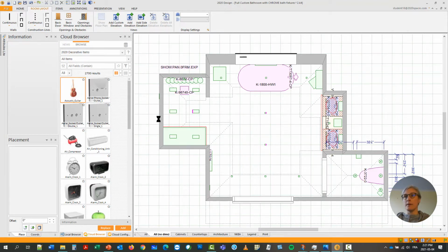The first step is to create a hole. But just before you create a hole, something that I recommend is to apply the texture that you need on the wall itself. So when you create the cutout, it will wrap the texture inside the hole. Like this, you will not have to add several pieces of surfaces to get the same goal.